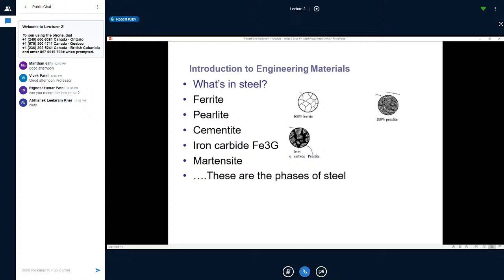As we add carbon, now this is a different piece of steel. You can't turn this into something else. So this is done by the manufacturer. As we add carbon to steel when it's produced, the carbon starts to put in these little lines. And if you notice, this is still 100% pearlite, which means it's saturated with carbon within the crystal structure.